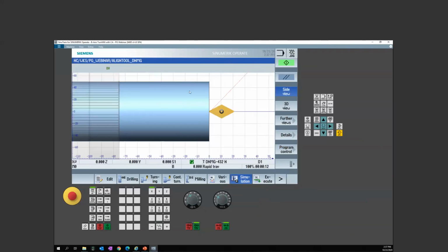So first things first, the system came down, positioned to B0. If I look at my insert, it's dead center on my x-axis. Now I back off. I'm going to do an orientation change, and I'm going to 62.5 degrees. And that's an important number, so kind of remember that one for a little while.